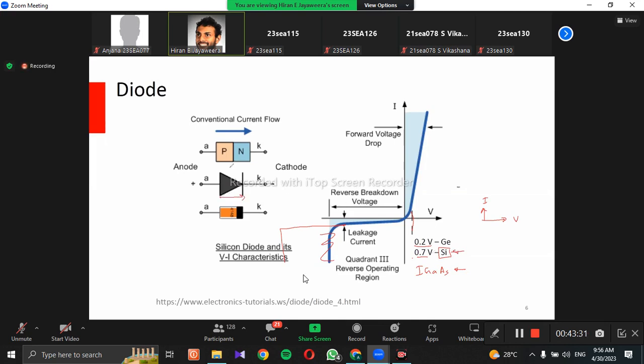So this is the circuit symbol. This is how the PN junction is arranged according to the circuit symbol. And usually with a diode, you will see some sort of line. Depending on the type, it could be a black diode with a silver line or a transparent casing with a black line. This line is basically your cathode. So the line on the real device marks the cathode.